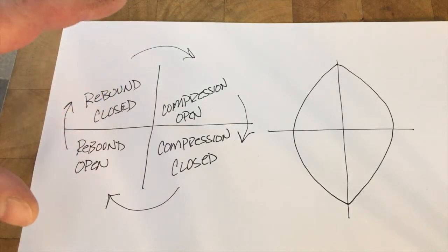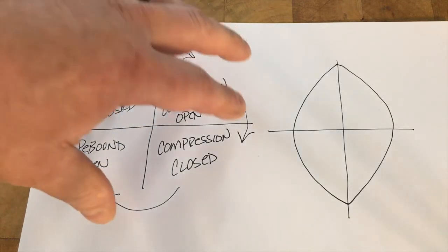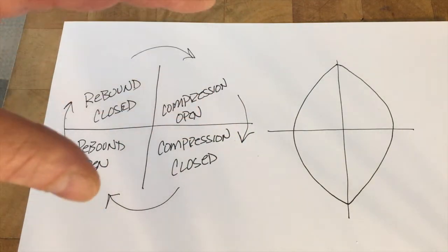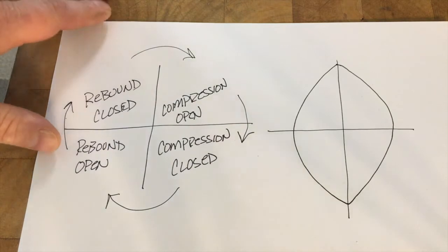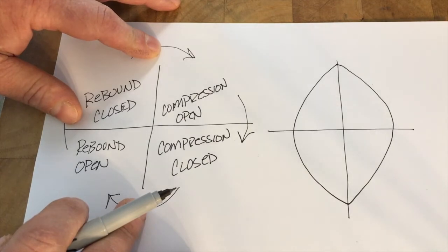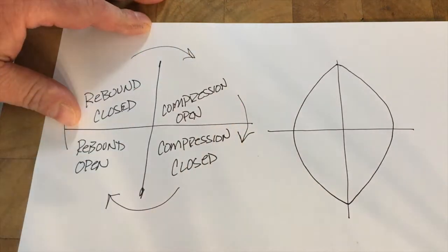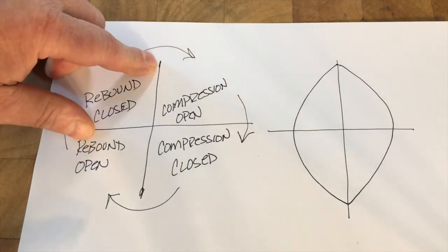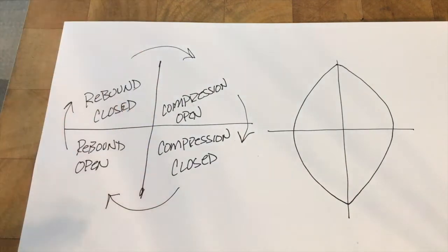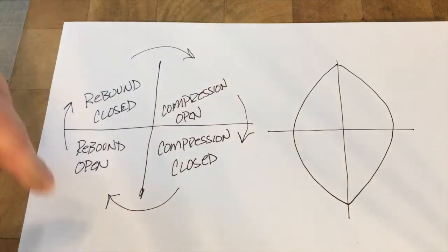You're going to get a dyno graph from a pencil operated dyno, a pen operated dyno, similar to this. Think about it as a crankshaft going, because these are crank dynos. Like we talked about in the speed and time video, I do another video on speed and time, and it operates on a crankshaft. This portion up here and this portion up here will be the slowest moving. You'll actually hit at this exact point, and at this exact point, there will be zero movement. At some point here, the pen or the shaft will stop totally and change directions, and it'll be traveling this way.